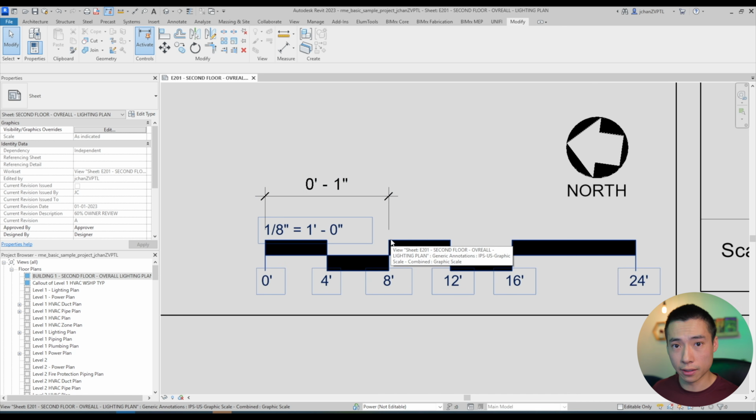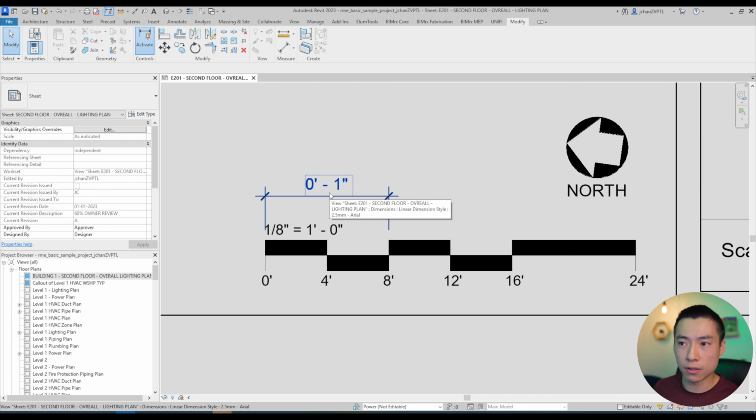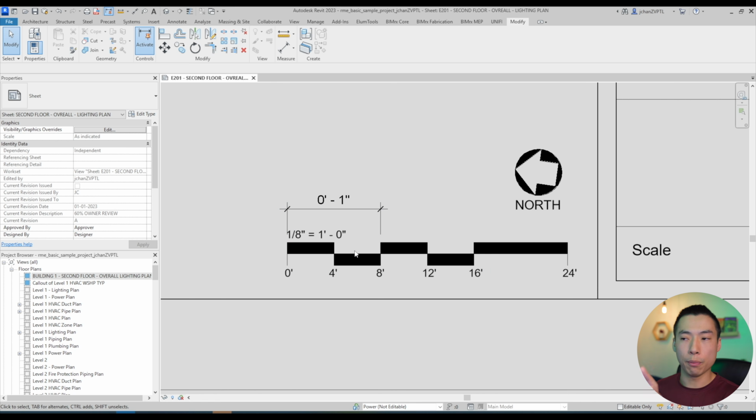And if it comes out less than an inch, that means that your drawing has been printed at 50% scale or some other shrunken number. So like if this measured out 1/2 inch, then I knew that it was printed at half scale. So that's why it's always important to put a graphical scale on your drawing.